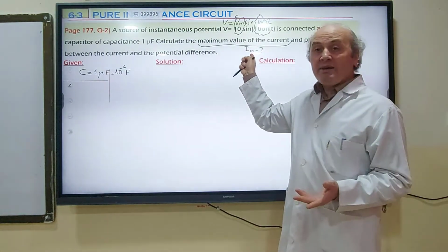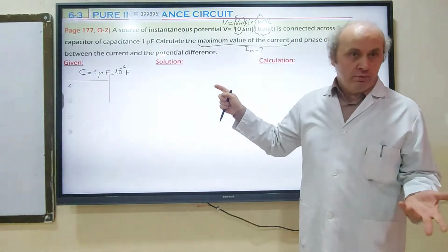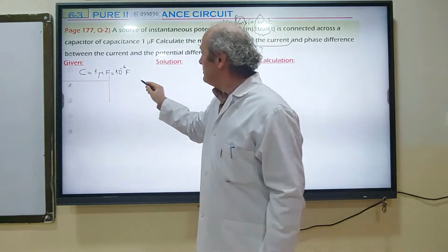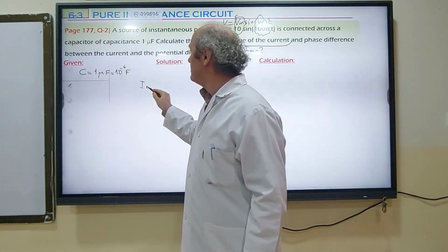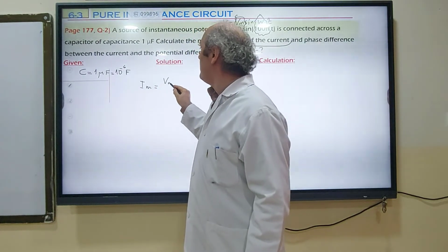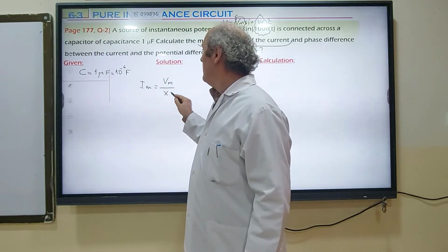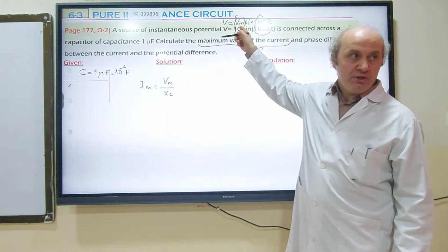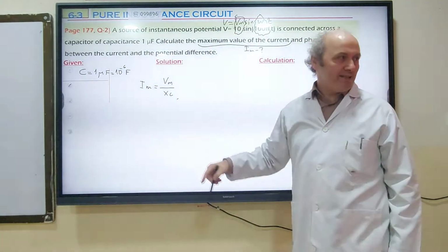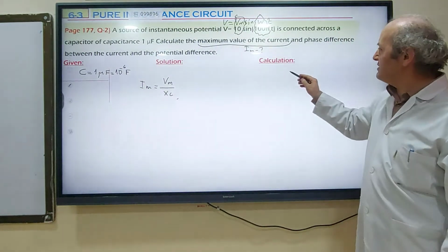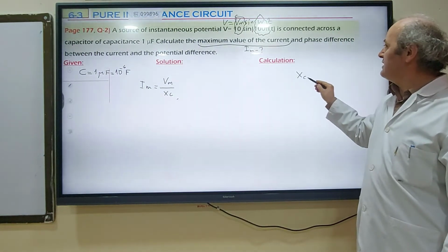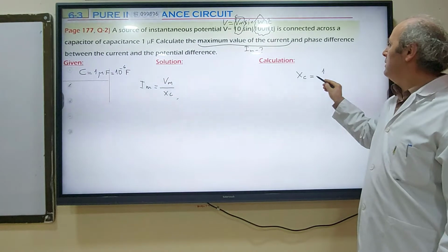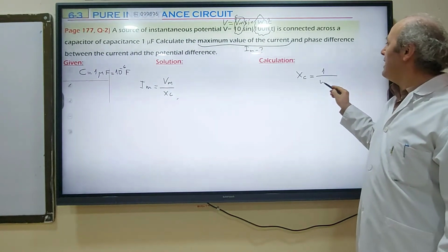But IM can be calculated by Ohm's law. So Ohm's law tells us IM is equal to Vm divided by Xc. Vm is from the equation we got, which is 10. But I need to know what Xc is. Let's calculate Xc first. Xc is 1 over omega c.